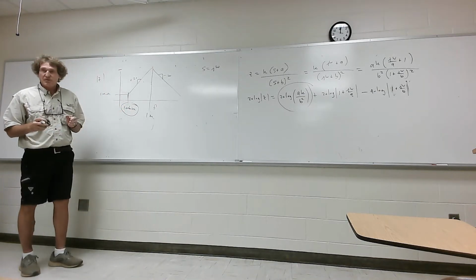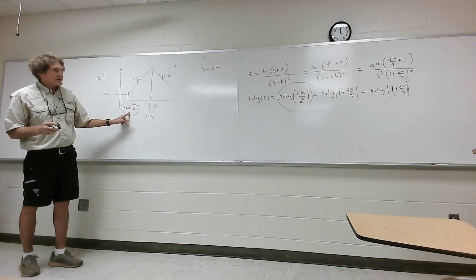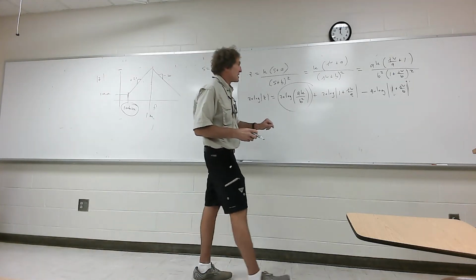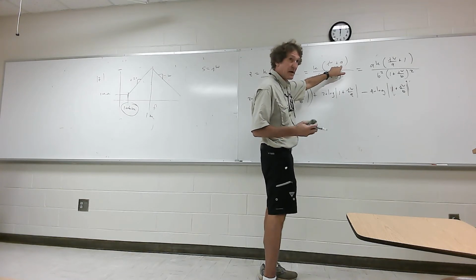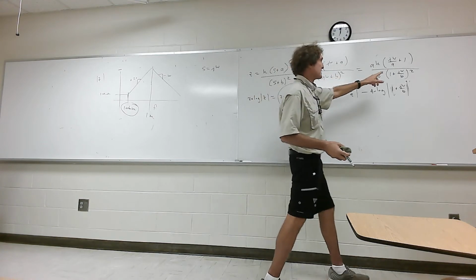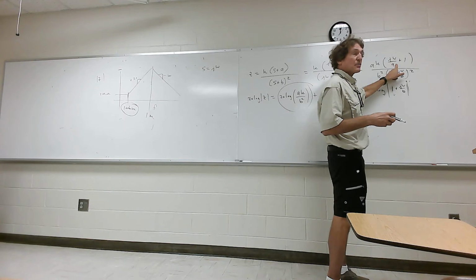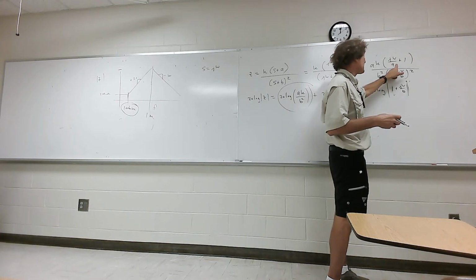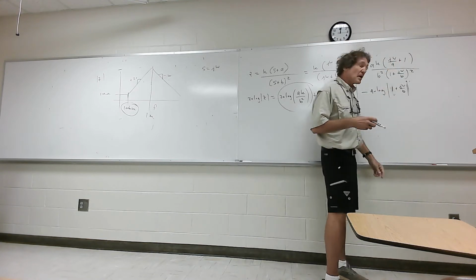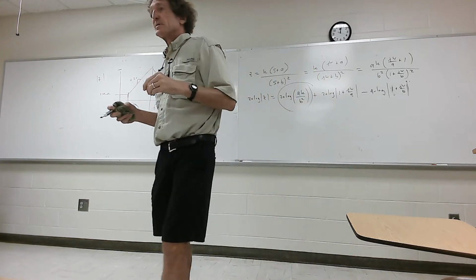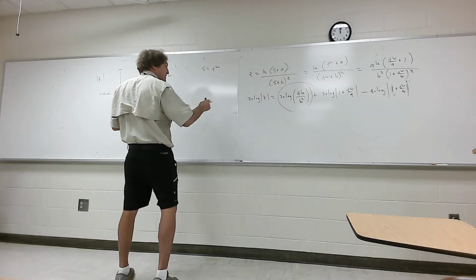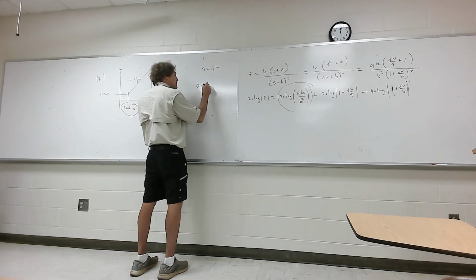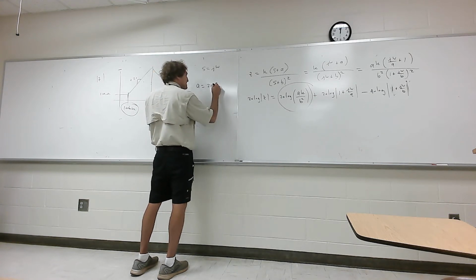Now the next thing is, you have to realize what we do with this number. That is the first zero that starts the thing ramping up. It's at 100 kilohertz. That tells me that this value of A here will be 2 pi times 100 kilohertz, because that's where we want the thing to become of the order. When you're at 100 kilohertz, 2 pi times 100 kilohertz, this thing right here will become a value of 1. You'll have j1 plus 1, or magnitude square root of 2, and that's where these things cut in and out. Follow me, everyone? So we come over here and we can say that A is going to be 2 pi times 100 kilohertz, or just times 10 to the 5th.